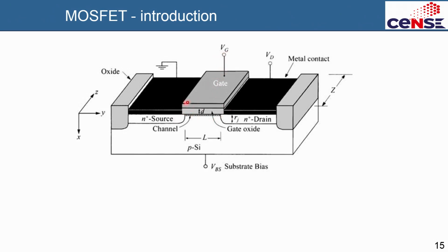You can also design the transistor such that if you apply a small RF signal here, you might get a very amplified signal here, in which case it will be like an RF amplifier. In some cases it can be like a power switch, where you have to block a very large voltage and conduct very high current. So there are many kinds of applications of the MOSFET, depending on design and many other aspects, but the basic operation is the same everywhere.